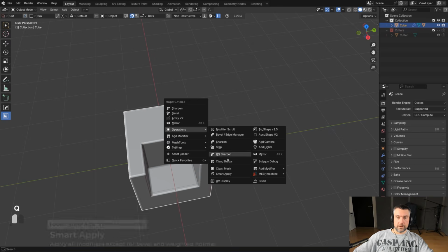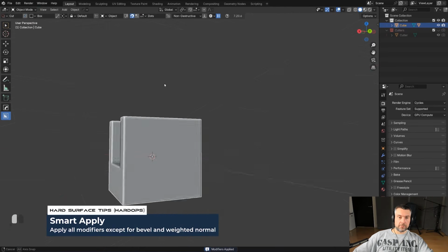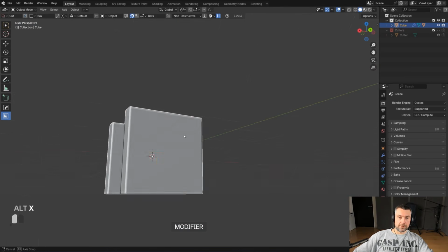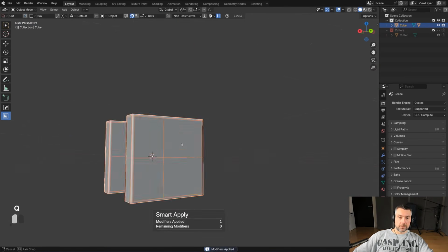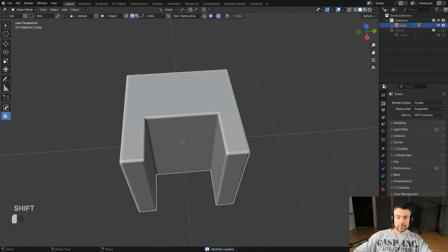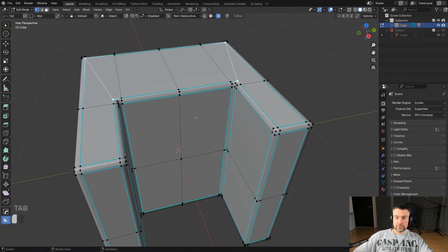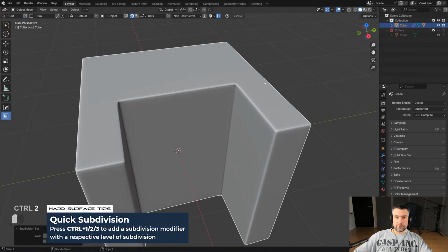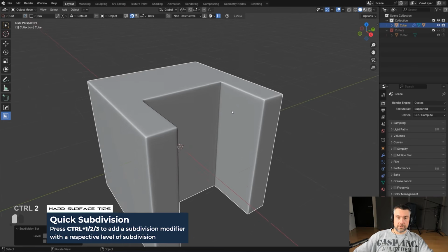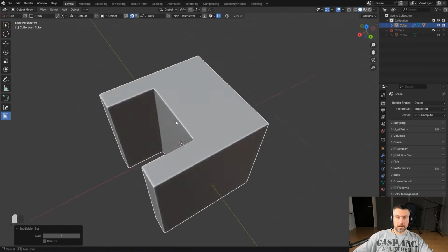I'm going to apply this, just multiply this, and also I'm going to mirror it to the other side of the bottom because it can be better fixing the bottom. So again, multiply, and now I got my mesh sorted. Okay, so watch this. If I'm going to apply Subdivision now to this mesh, it's going to work. If I press Ctrl 2 to subdivide it, everything is fine. Even Ctrl 3, you get a very clean subdivision on your mesh, and you don't have to worry.